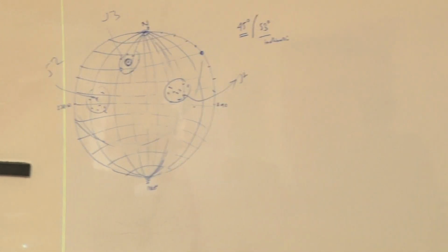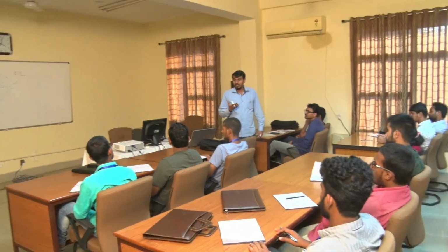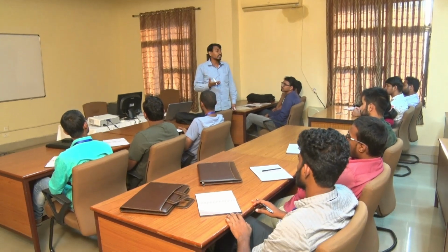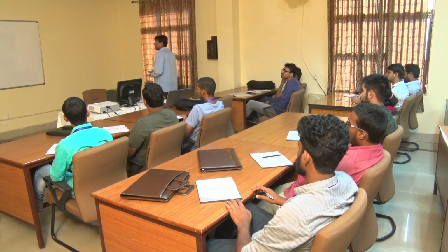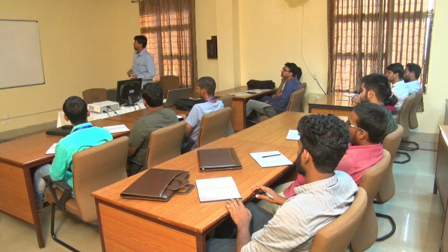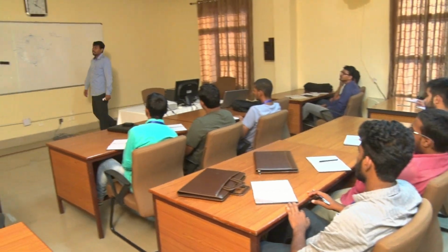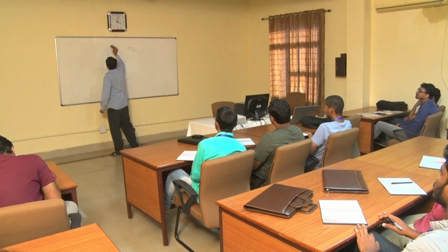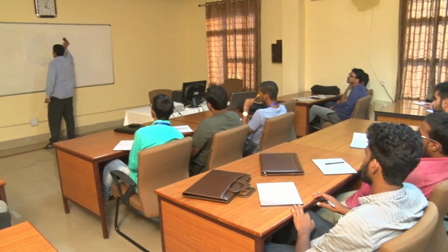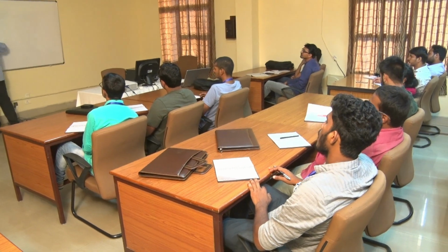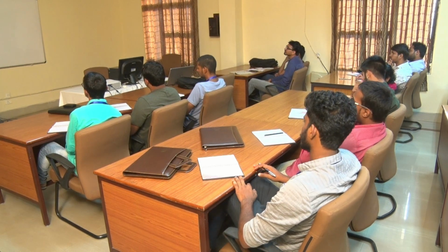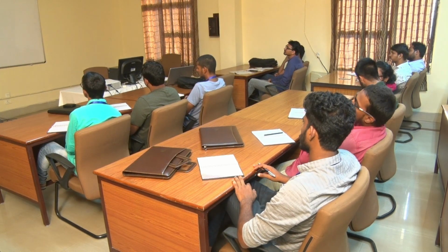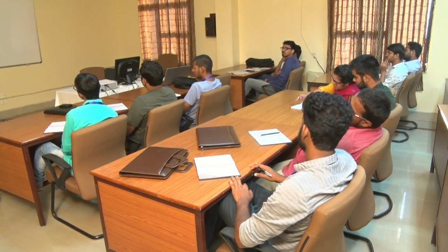So the help of the stereonet is, from the stereonet plot itself, you can easily assess where the concentration is more for the joints. So basically this approach helps a lot for analyzing different problems related to rock slope stability. In slope stability, we often use this stereonet to calculate initially the stability condition, because in the stereonet we have a procedure. There is some condition we use.